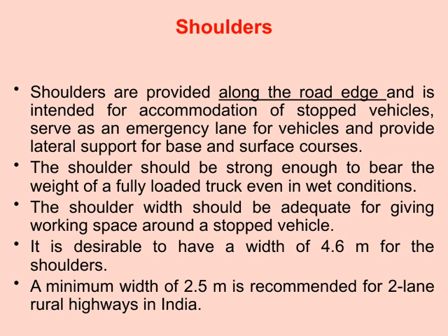It's crucial that the shoulder is strong enough to bear the weight of a fully loaded truck, even in wet conditions. This ensures safety and durability, especially during adverse weather. When designing shoulders, the width is also a key consideration. It should be wide enough to give enough working space around a stopped vehicle, allowing for safe repairs or emergency stops.